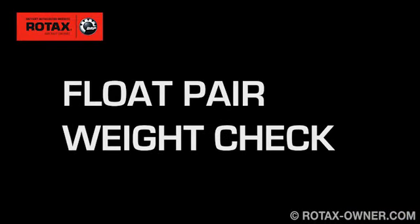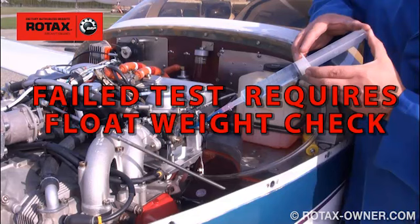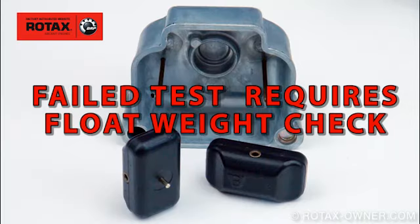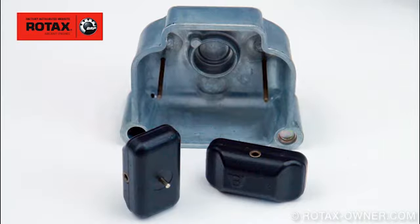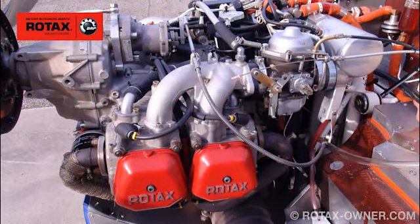If the inspection of float buoyancy shows a deviation, then a check of the float pair's weight is necessary. For this purpose, the float chamber has to be dismantled and the floats need to be removed. We'll demonstrate this procedure on a Rotax 914 series engine.